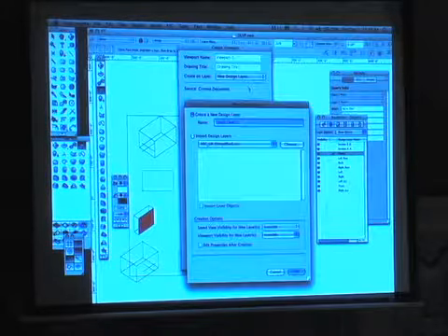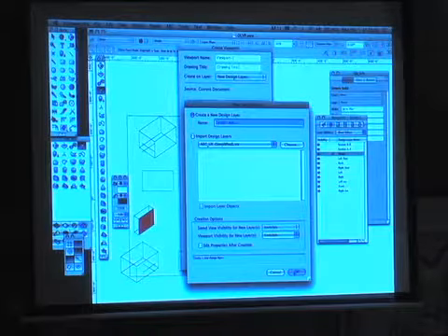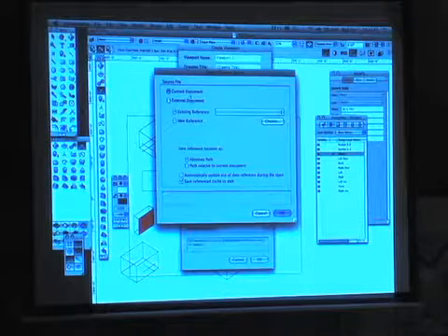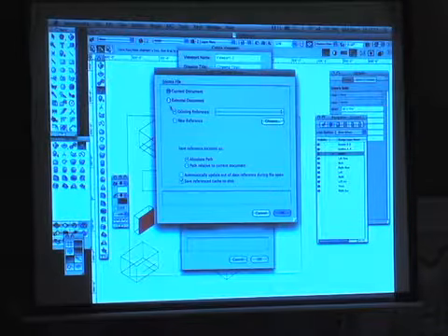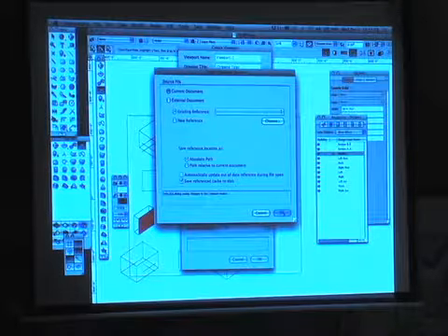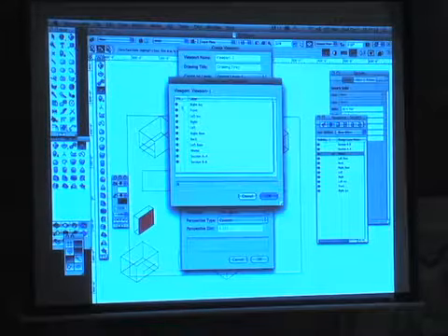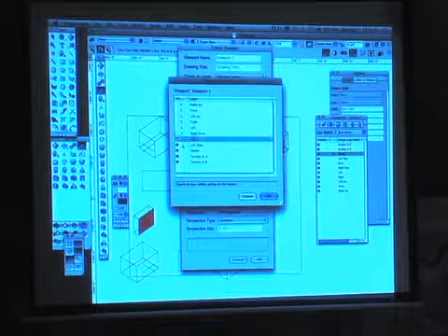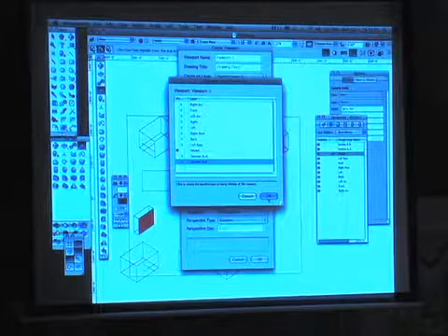So I'm going to say a new design layer, and I don't know what we'll call it. We'll just call this design layer 1. And the source, you can put it in a current document. This is great for bringing in pieces of an external document. When you're sharing a file across the office, you're able to bring in pieces of a drawing from somebody else. But we're just working here within the same drawing. And again, just like any other viewport, you have the ability to turn on the layers and classes. So here I want to turn off everything except my model, because when I create that viewport, it's going to show all the other layers in it. I just really want this model to be the focus of my viewport.